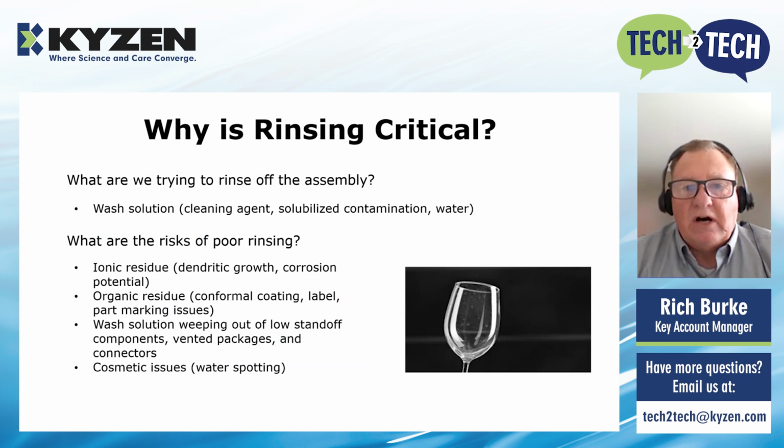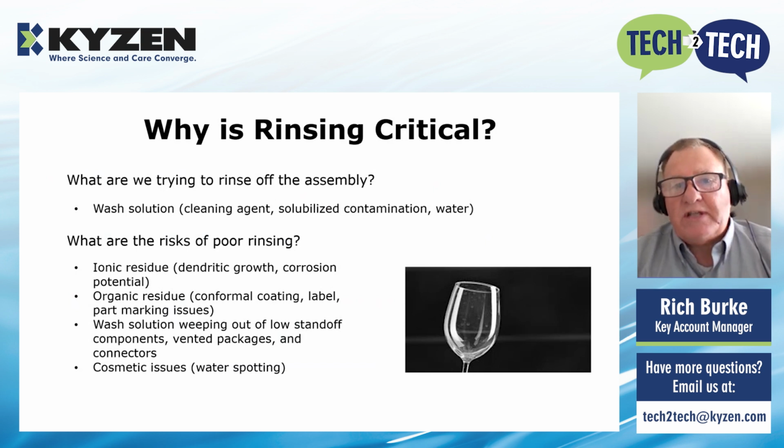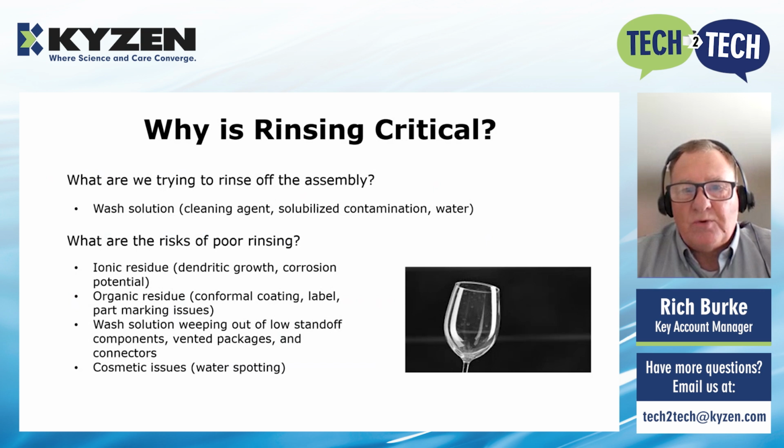The wash solution itself is designed to get into tight spaces. If we're unable to rinse that material out, we can see, over time, weeping of the wash solution from under low standoff devices, vented packages, or connectors. And then lastly, we can see cosmetic defects. We've all seen water spots on glassware or our vehicles after we do a car wash. It's the same thing. Cosmetic defects can be an area of concern, and poor rinsing can lead to them, including water spotting.